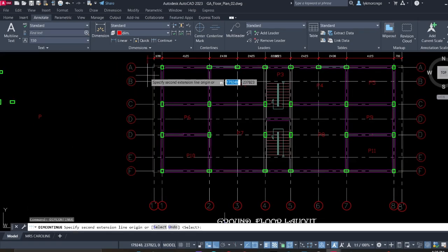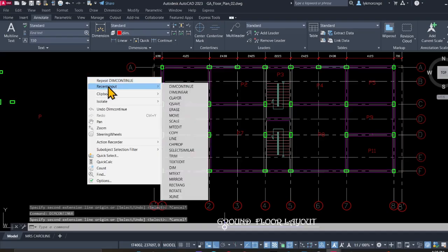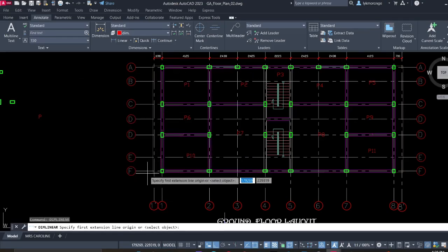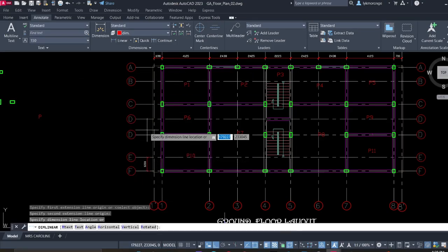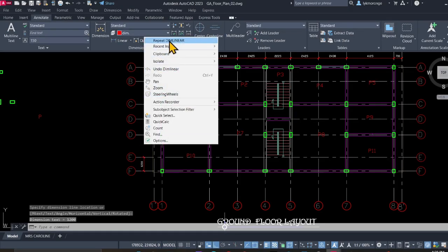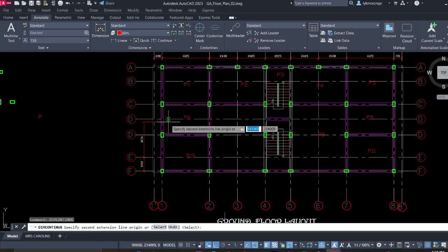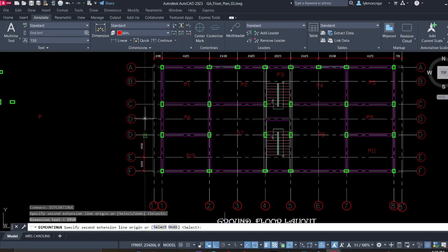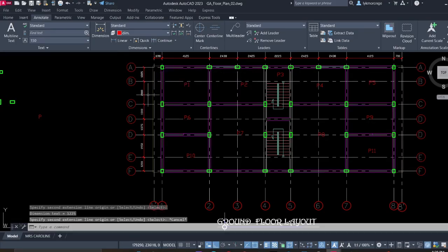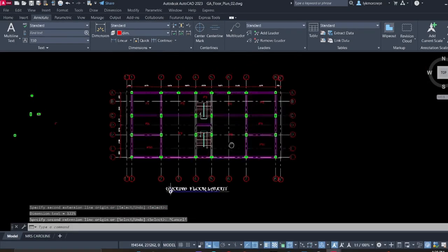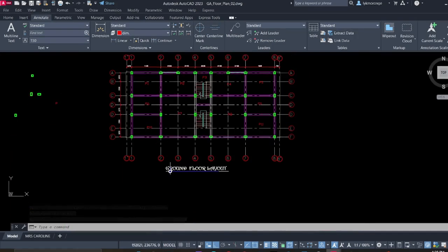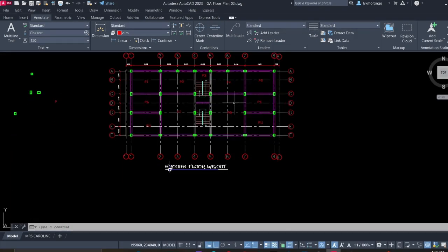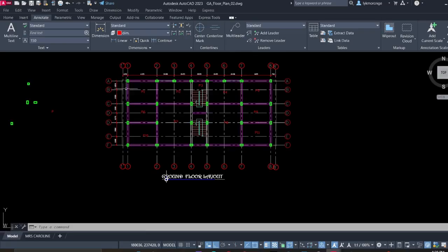Now you can proceed up to that level. Now we have your dimensions done. What else have we left? Now is just to save this our model as a DXF file, and then we just export it to ProtaStructure.